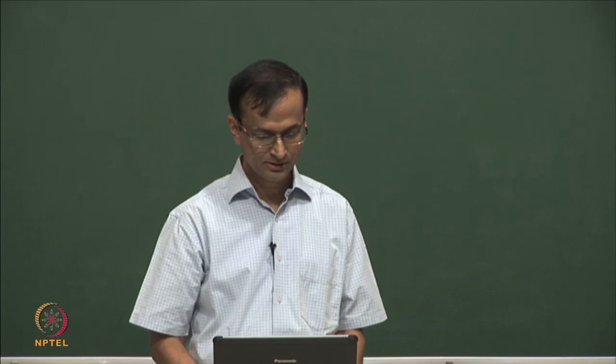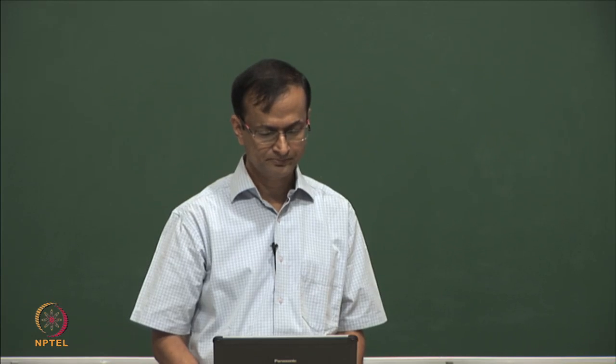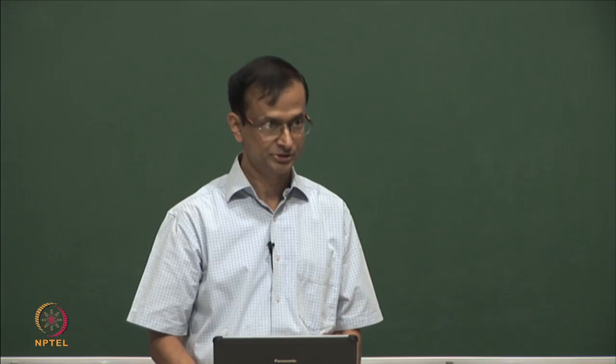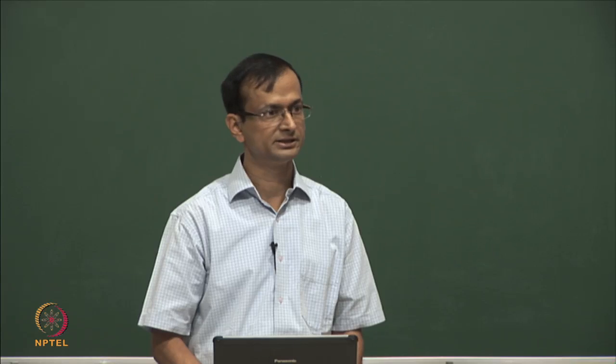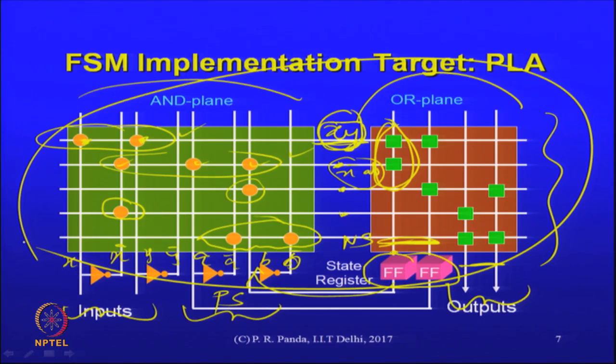Number of inputs, just number of inputs? Number of columns is determined by what things? Number of inputs and number of outputs also, because those are also occupying space, right. There is a column dedicated to every output. So, these are determining the number of columns. Number of rows is determined by? The number of expressions we add. Number of minterms. Can you be more precise?